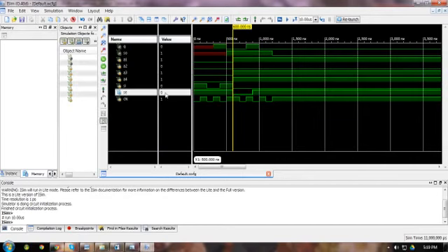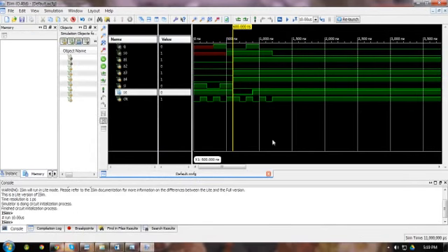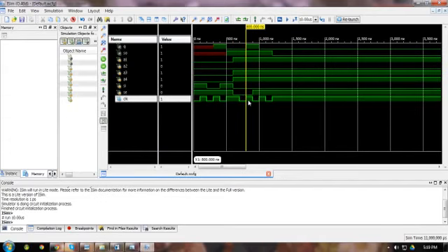Let's go back to the simulation. Okay, so after the first clock cycle, second clock cycle, third clock cycle, I have made scan enable equal to 0. Here you can see the scan enable is 0 now. It means now the responses are captured. You go to the RTL, it means the output of this AND gate gets captured here, the output of this AND gate gets captured here.